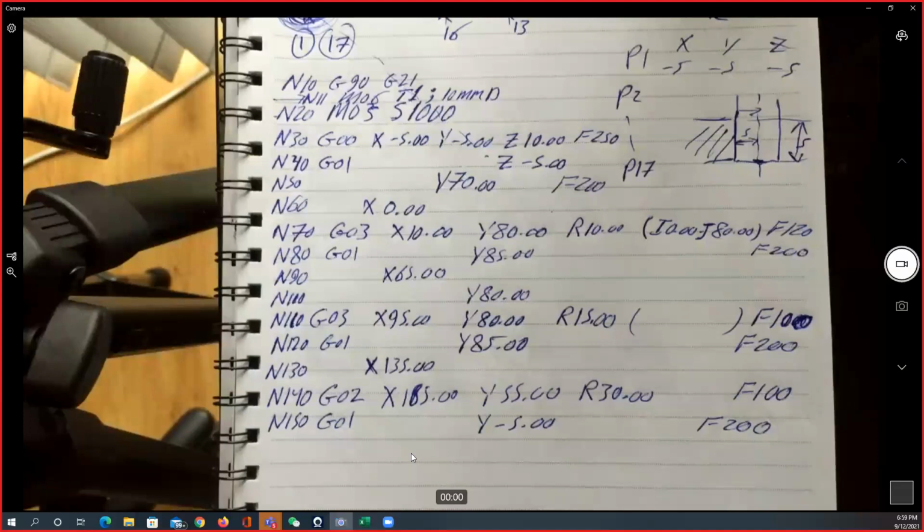Now, how fast you go for the RPM or for the feed rate is a very tricky thing. It's actually a study done by Taylor, who made the Taylor formula for the tool life. He said you can cut faster, shortening the time of the machining, but you will sacrifice your tool.